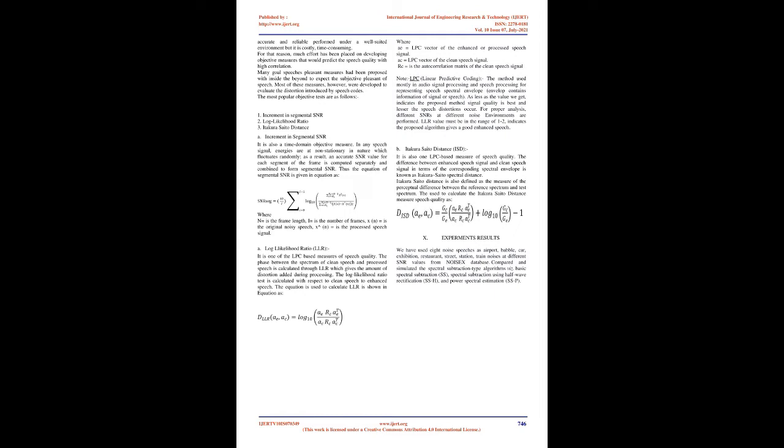Since we didn't calculate for phase information, it can be used to transform the frequency domain to the time domain. The phase of the noisy signal is combined with the processed magnitude spectrum, and then the inverse fast Fourier transform is applied. By multiplying conjugates to the speech signal, retain the real part because of the conjugate symmetric property, and overlap add processing to get the pure speech in the time domain.